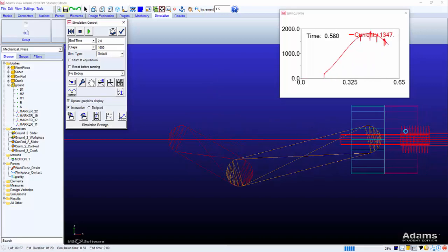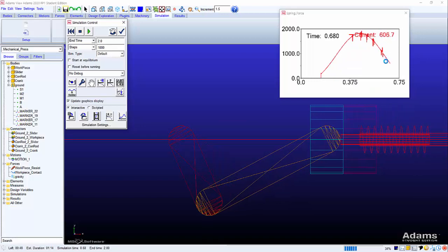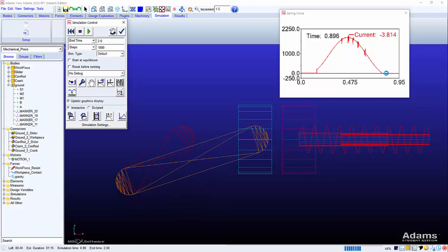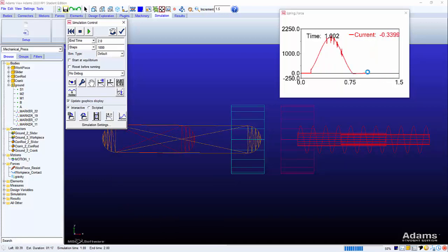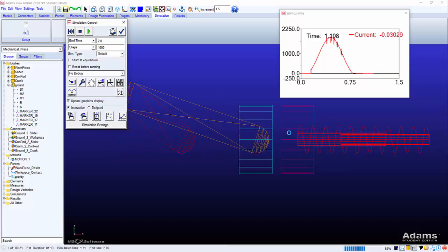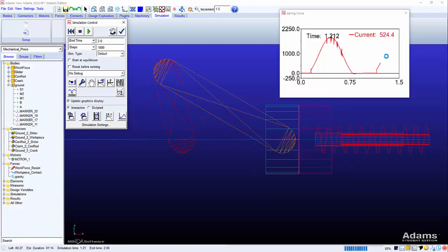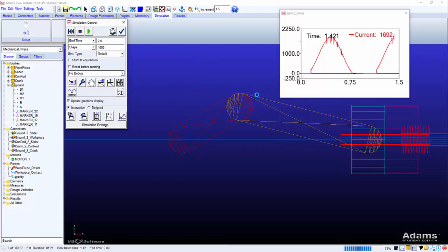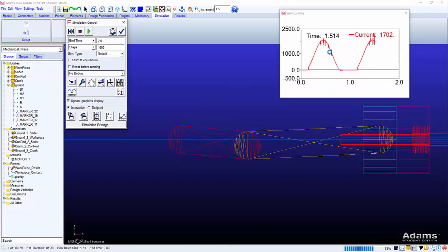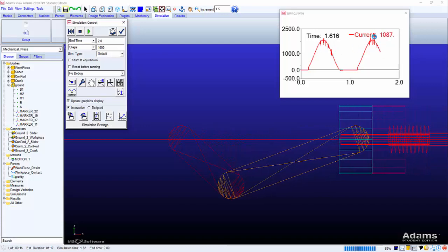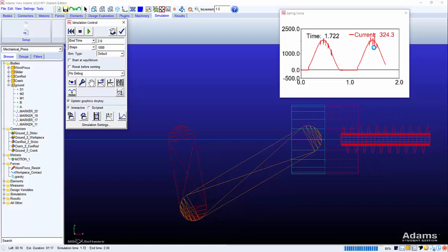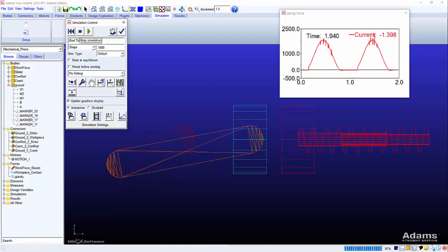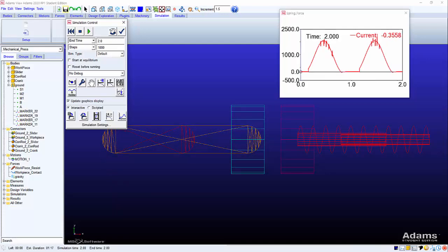Now once it starts to retract, the contact force is decreasing until they become right here, no more contact, so the spring force is equal to 0. And now the piston is going to continue for the second cycle. Contact will start again, and as you can see the spring force is increasing. The spring force is much smoother than before. We still have some irregularities, but this is acceptable because of the stiffness pushing against our contact. And now the simulation is complete. I'm going to save this simulation model